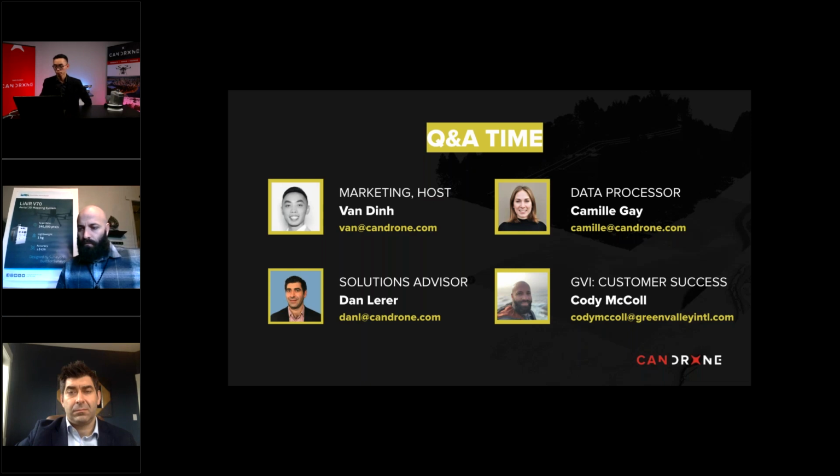Yeah, so LiGeo reference is specifically for GreenValley International customers who have a LiDAR V or LiDAR V70 or one of their LiDAR systems, and need to do that point cloud creation process. The main reason you need LiGeo reference would be to make that point cloud where you combine the IMU, the GPS, and the raw laser data into that point cloud. Once you've created that point cloud, you can for sure take that LAS or LiData file and bring it into LiDAR 360 and do the rest of your processing there.